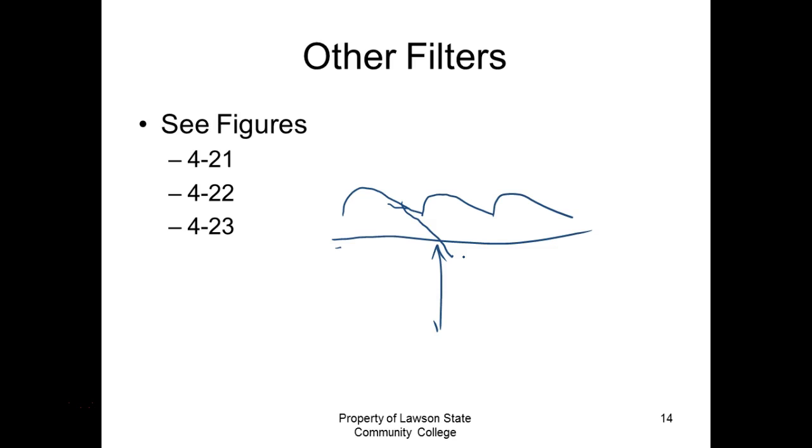Does that make sense? Yes or no? Make sure the ripple voltage doesn't drop into your regulated voltage. Huh? I thought that's what the regulators do. It can't get out more than you give it, right? If you don't give it the voltage that it needs, it can't add voltage, it can only take away. That's all the regulator does, is clip it off. It can't take care of the ripple voltage.